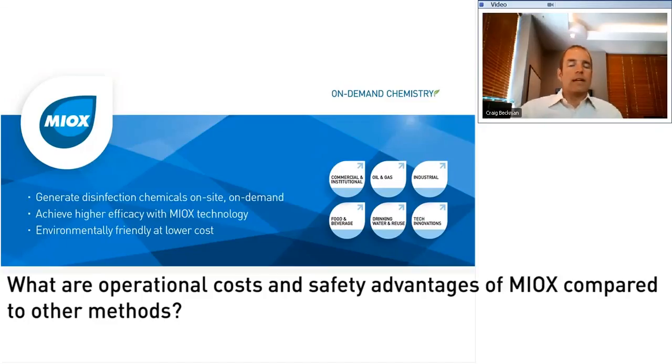From a safety standpoint, we feel we're far superior to most all biocide chemistries, because the bulk ingredient is dry salt. And from a spill avoidance standpoint or an EHS handling standpoint, salt is obviously much safer than most of those biocides, even in dilute concentrations. And even the output of the generator, because we produce at under 1% at a relatively neutral pH, is still safer in most cases, especially than gas chlorine, for example. So we see superior safety benefits and very often cost benefits for many applications.